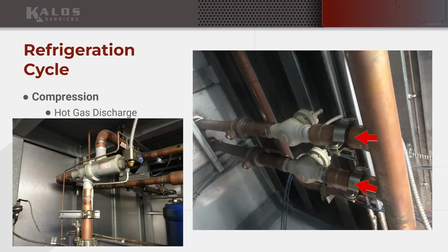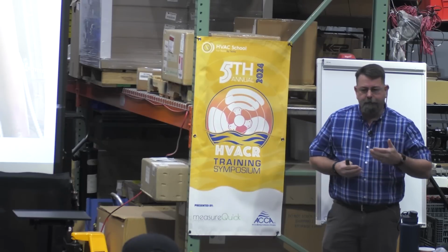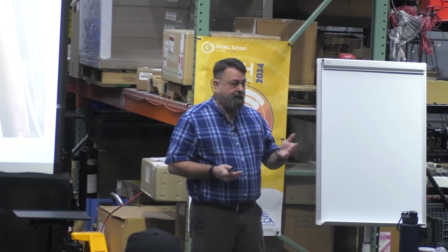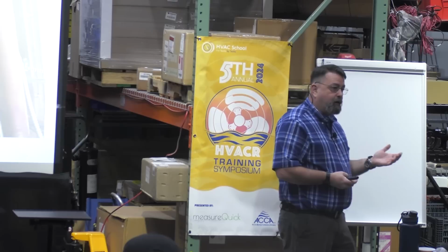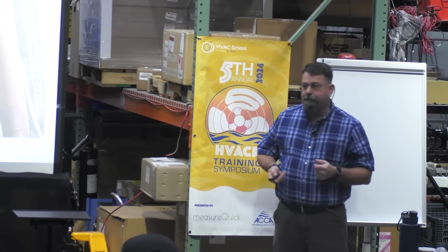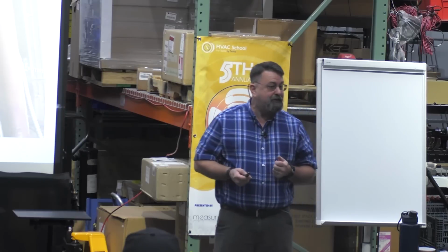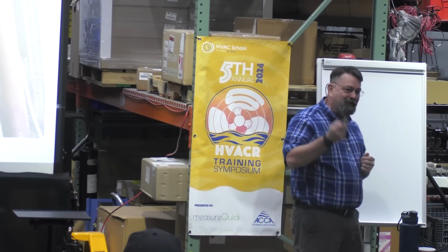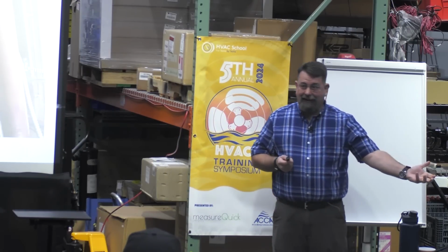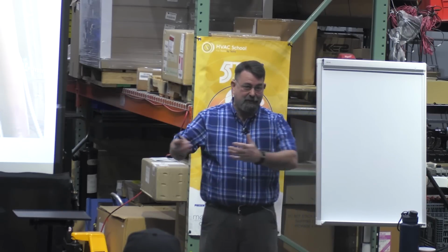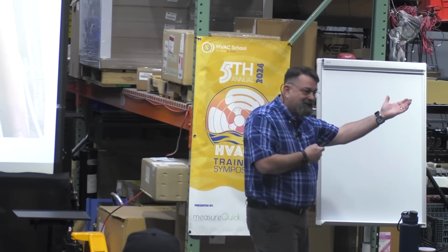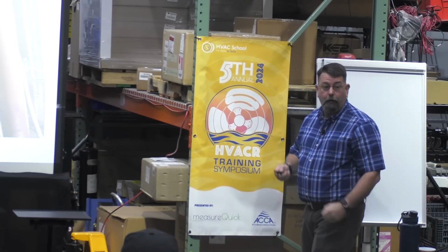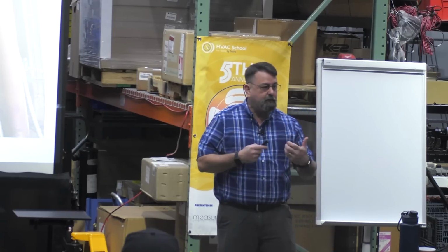So a very common thing that we do, your air conditioner, if you got straight AC, you're probably not running that in January at 2 o'clock in the morning when it's 17 degrees outside, right? Well, we are going to run refrigeration, right? Because we still need that ice cream to be frozen. Even though we're heating the store to 68 degrees, I got to cool this stuff down to minus 10 because the store is at 68, even if it's minus 10 outside, right? So that means I've got to be able to run my rack in low ambient conditions. That's a little bit of a change there.